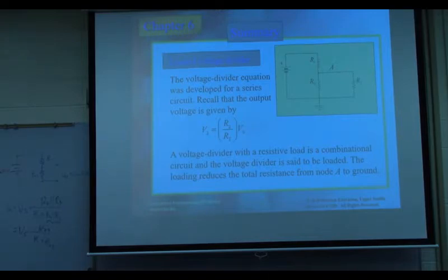Is this true? For example, I give you 10 resistors, all in parallel. Very simple parallel circuit. These 10 resistors have different values. One must be the minimum, for example 1K, and the others equal 2K, 10K, or bigger. Then I claim the total is less than the smallest.